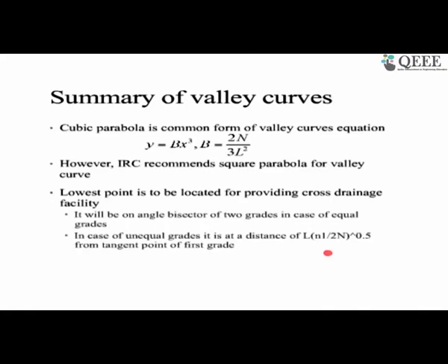This enough distance is going to be an extra lane which you are going to provide on the side of the bus stop. If you have enough distance, the bus can come out of the main lane and go to this deceleration lane, and in the deceleration lane it will slow down and come to a stop. So this is what you have to take care of, and this can be calculated based again on the stopping sight distance, so your deceleration lane should be at least of that length. I hope I answered that one.